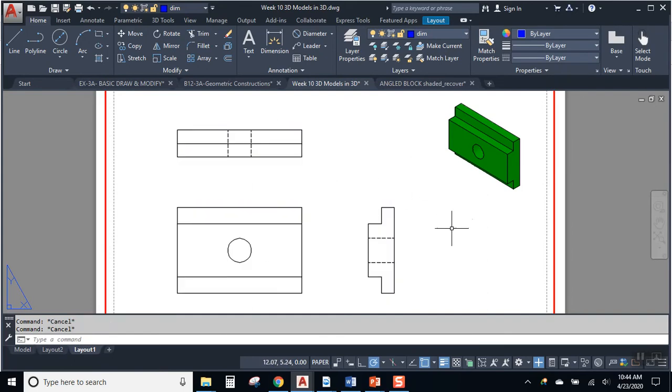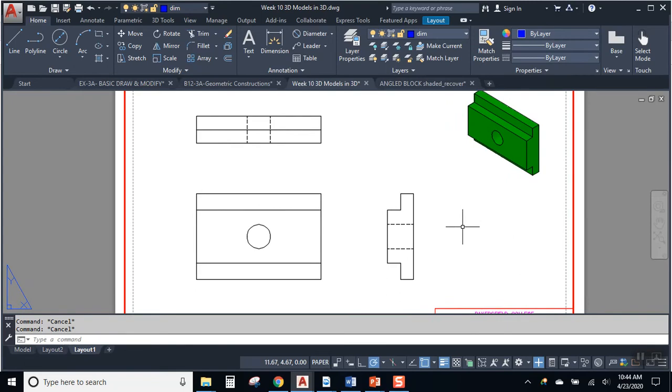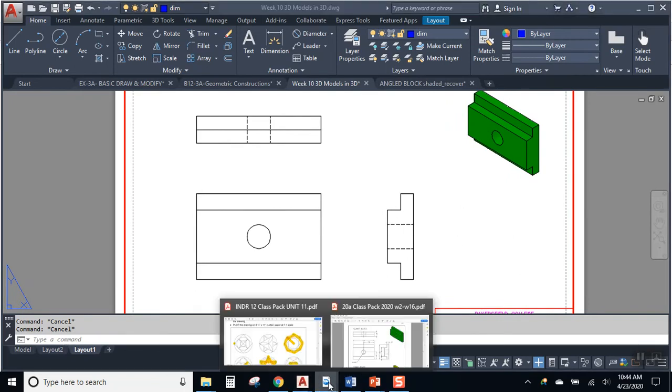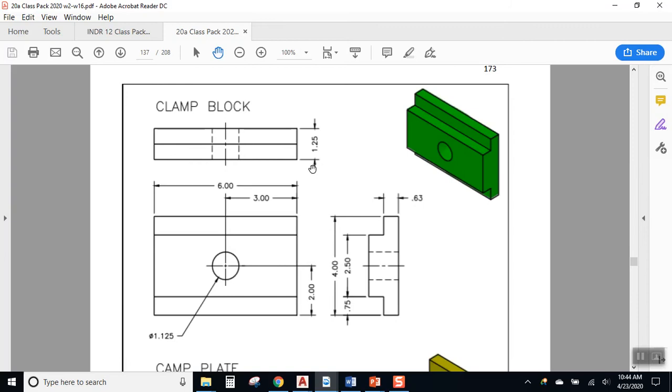All right. So what else do we need? Well, let's go take a look over at that file here. So when you get a drawing like this, when it's time to add dimensions, this shouldn't be too tough. We're going to use the dimensions that are here. And you can even use the dimensions I gave you kind of like a reference on what you need to add and where to put them. Additionally, we need center lines through the tunnels and center marks on circles.